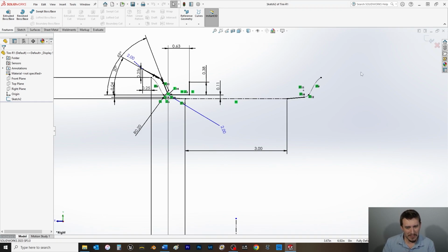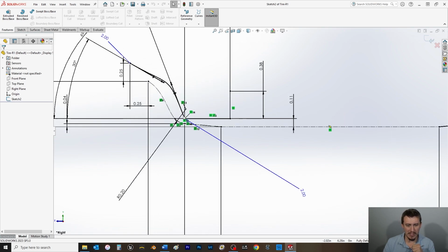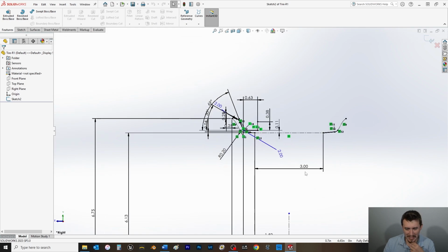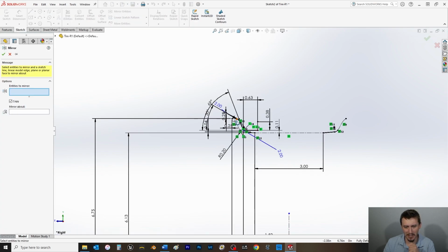Alright, so we left off kind of tinkering around with some splines and defining those, and kind of borrowed some profile geometry off of a different part to give us kind of boundaries, and that'll give us some offsets here. And so with that, we come across a unique thing that I was experiencing last time, which was mirroring certain parts of the sketch, and it causes conflicting relations.